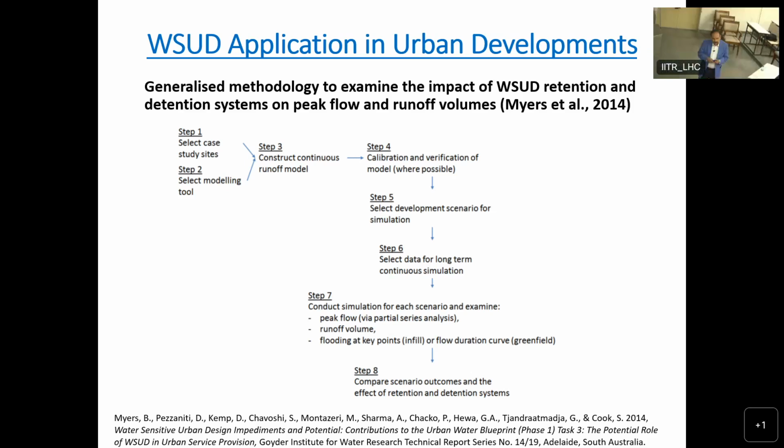Or other question, if you are looking for a larger area for your modeling and you have some data available for a smaller catchment of the same big catchment, then you can calibrate and validate your model for the smaller catchment, and you can use all those variables and parameters. Although the situation or the outcome can be slightly different, at least you have some basis to justify your work.